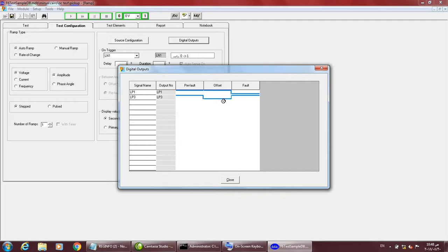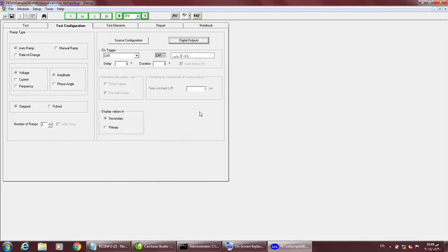This is useful for auto reclose test. This is used for giving the status in any test type, mostly in scheme testing. If you are doing scheme testing like carrier send, you want one contact to be NC and it sends carrier to the other end. So in that case, basically in scheme testing, not for normal testing. There is no requirement of that in any other test. Scheme test only.